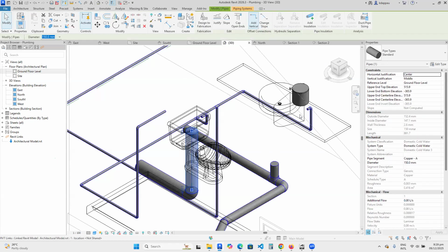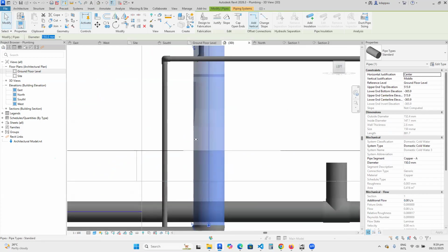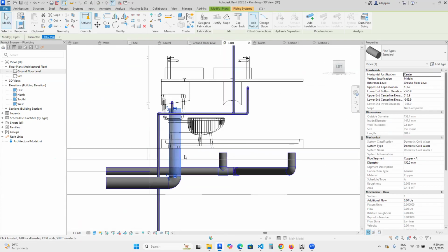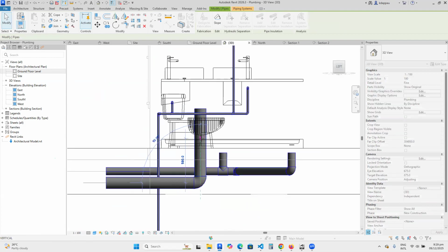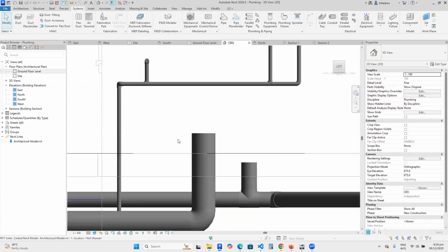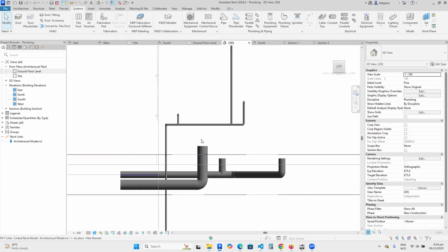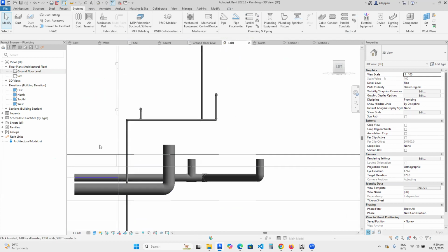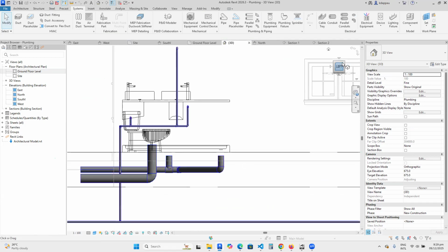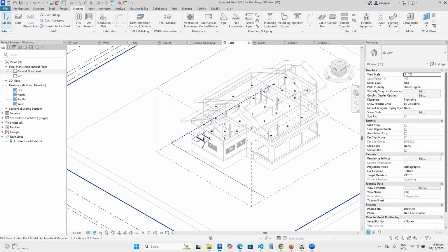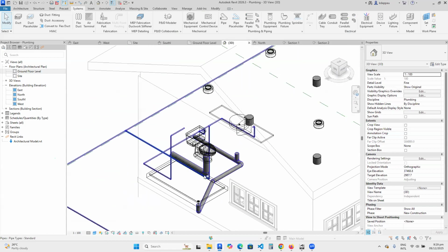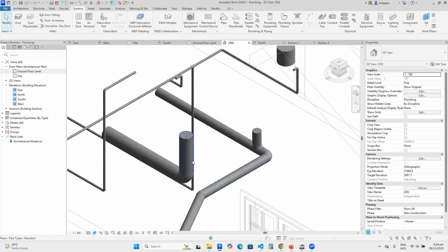And then this pipe here, I'll look at it from the side. Per the design of the WC, it should come here all the way, okay, to somewhere there. And then adjust the height. If it is P-trap, if it is S-trap, whatever WC fitting that you are going to put in, you know the exact position to place it from the wall. So I've done this one too, as simple as that. If it is a multi-story building, you must know how you can connect them. Any question?